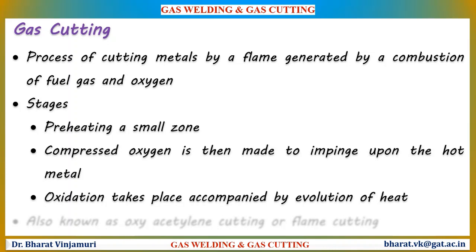Oxy-fuel gas cutting process involves preheating a small zone from where the cut has to be started. Compressed oxygen is then made to impinge upon the hot metal, resulting in very high rate of oxidation, which is often accompanied by evolution of heat due to exothermic nature of reaction.